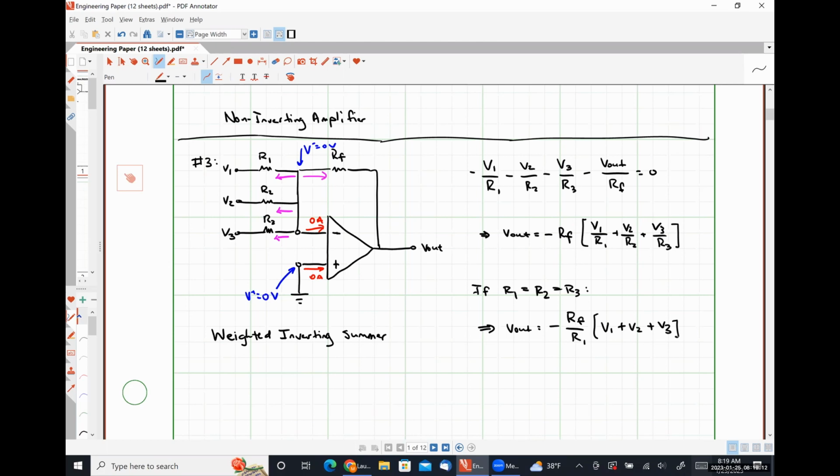If you have multiple load cells connected in a string, and then you want to add the output signals of all of them together to find out the total weight of a truck, this is literally the circuit that does it. This is also the same circuit that's used in your common electronic or digital bathroom scales and all of that kind of good stuff. If you ever want to add a bunch of signals together, this is how it's done, okay?